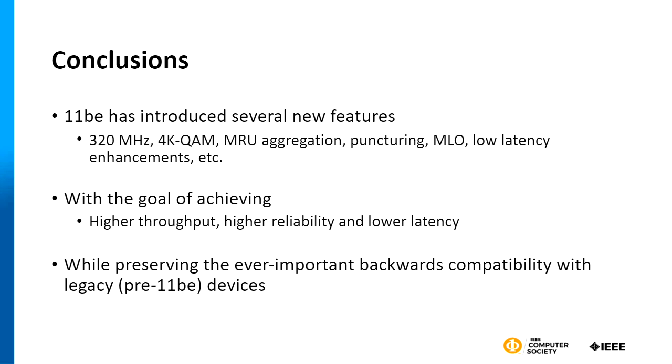So yeah, in terms of conclusion, 11be introduced a lot of new features. Some of them are 320 megahertz, 4K QAM, MRU aggregation, puncturing, MLO, low latency enhancements. And the goal was essentially to achieve higher throughput, higher reliability, and lower latency, while preserving the very important backwards compatibility with legacy devices. So I think that's it.